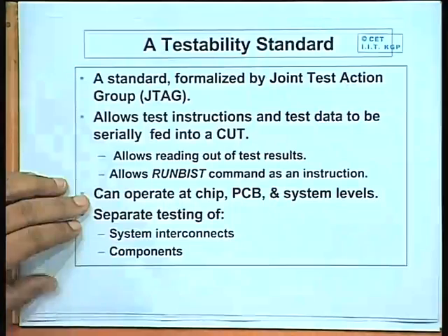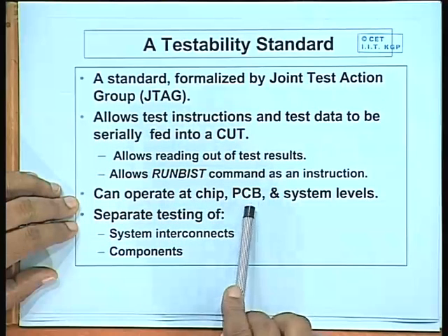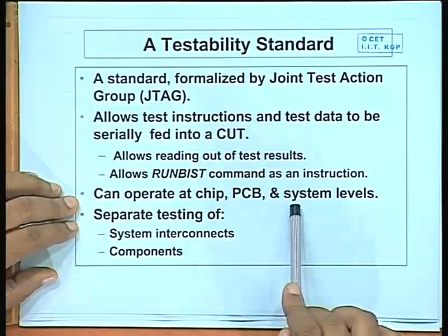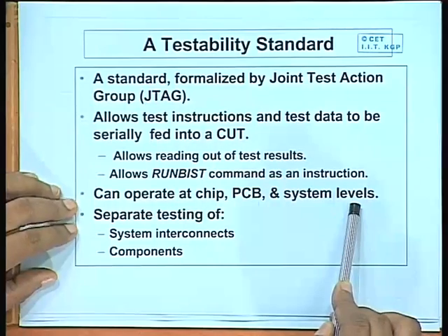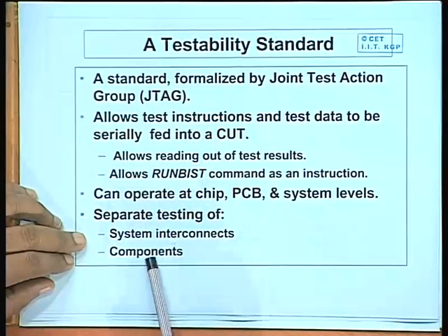JTAG is totally hierarchical in nature. It can operate at the chip level, at the board level, printed circuit board level, and even at the system level. JTAG allows the separate testing of components and also the system interconnects.